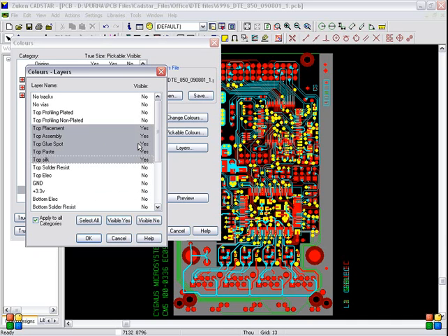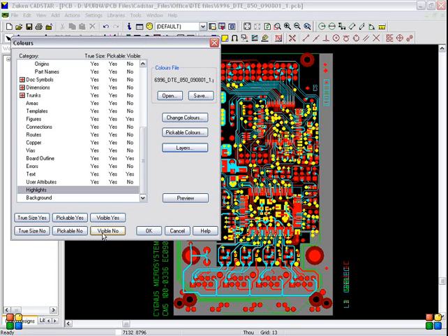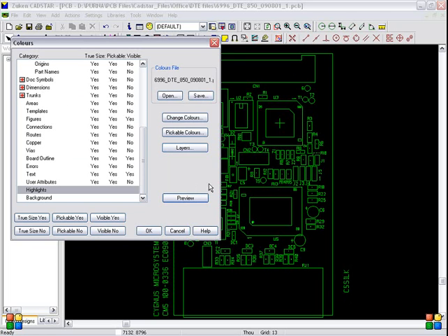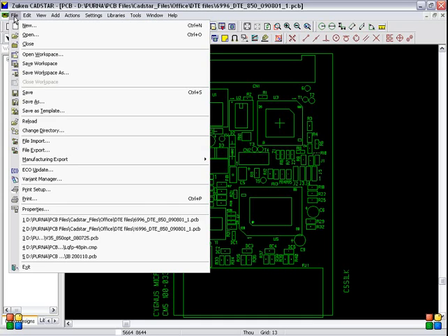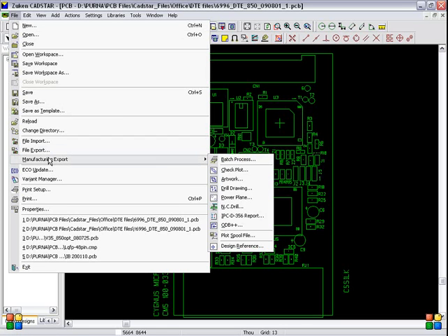This Gerber is for creating only CS silk. Okay, now click here, okay, and preview. After clicking preview you can see whatever you want for a CS silk layer, it will be visible, and click OK. Now refresh once, once again refresh, and come to the file menu, click file, and come to the subcategory manufacturing export. Here you have to click artwork.